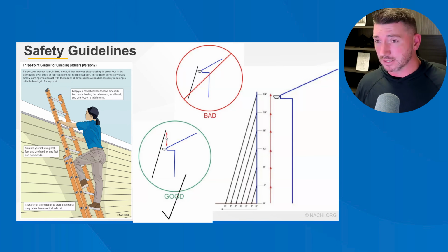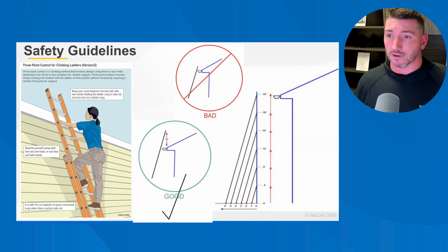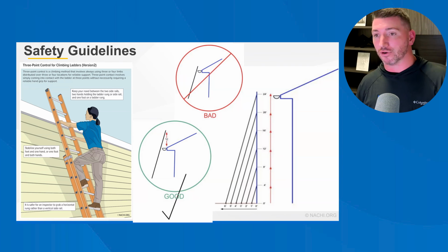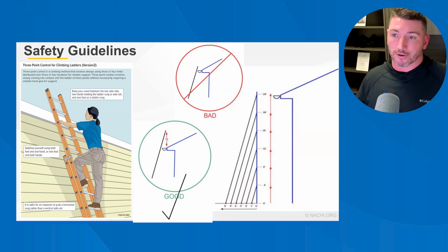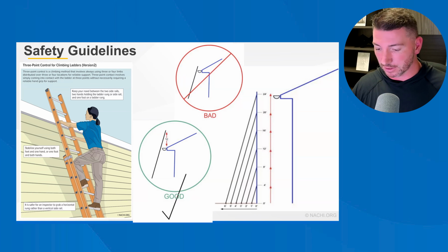The reality is there are such things as difficult access points. And when you're on an asphalt shingled roof and there's no gutter, there's not really a whole lot of good places to tie off to. So one thing I usually recommend is, if there is one, set up in a valley where at least you've got security in one direction. If the ladder's trying to blow into the other gutter, it's not going to fall down, but there is no 100% success rate there either.